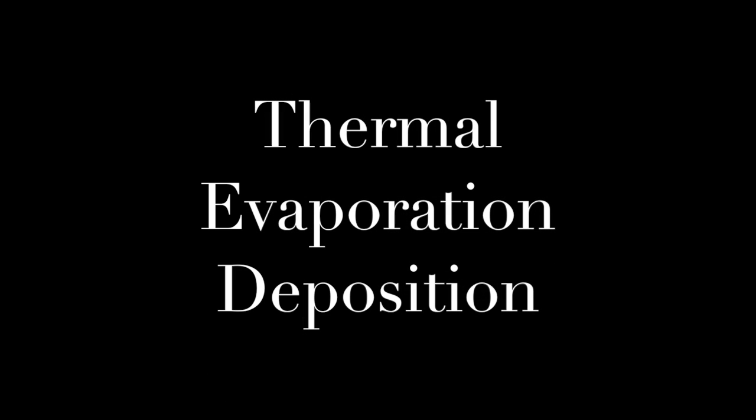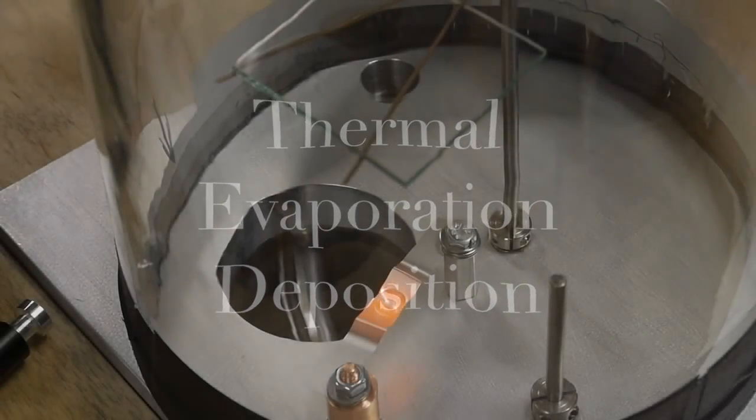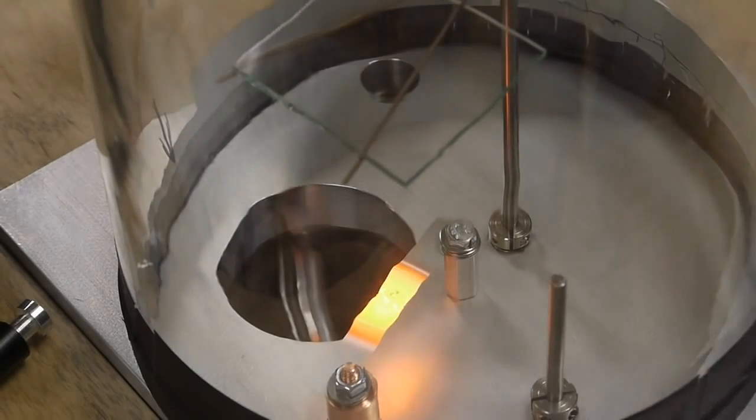Thermal evaporation is a physical vapor deposition method in which the source material is heated in order to cause evaporation. One method for heating is through an electron beam. Evaporated particles from the source travel to the substrate, where they condense to form the thin film layer.